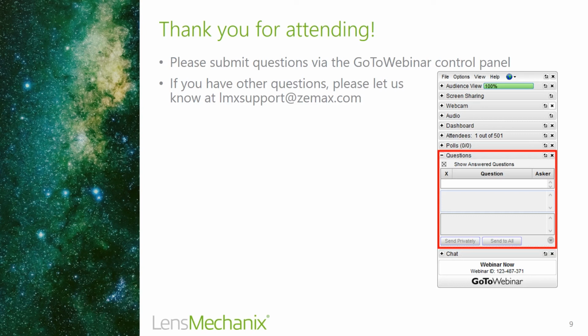Oh, this is a good question about coatings. Yes, so if you wanted to, and I mean, we have to figure there'd be some manual movement to do this, but if you added a fold mirror and you wanted to make it an ideal splitter, so if you're doing like a beam splitter, that's definitely possible to do with LensMechanix. Instead of using the ideal mirror coating, you would just use the ideal splitter. That also is shipped with LensMechanix.